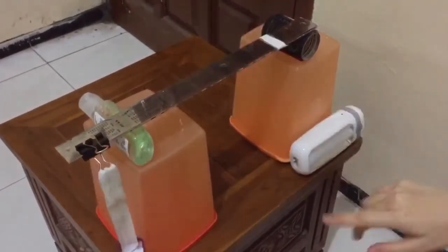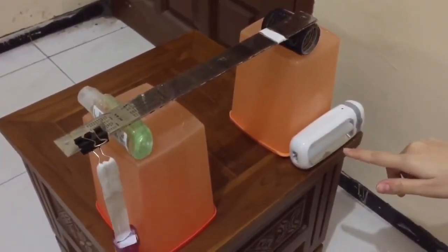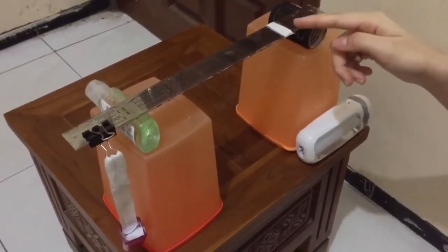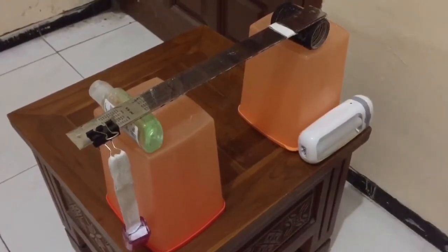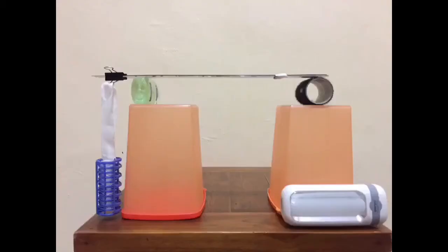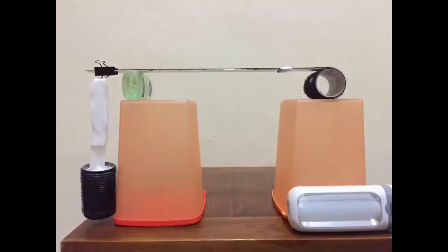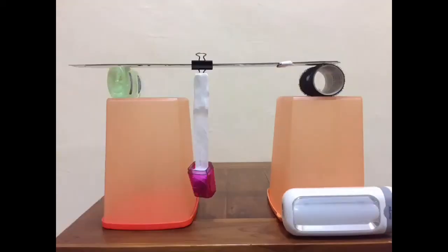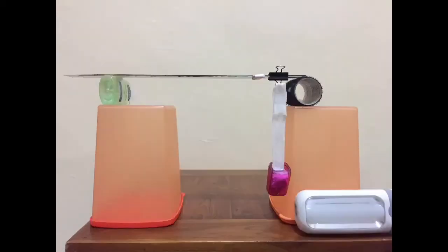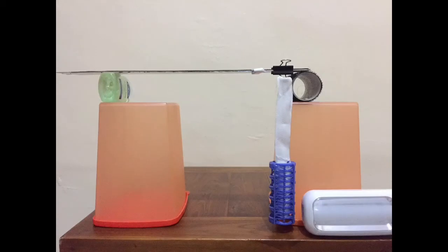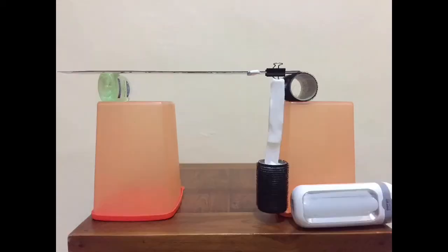After that, the display meter will show the shear force at this section, the X-X section, and the value we record on our laboratory sheet after multiplying it by -1. The experiment is repeated by increasing the load to 200 gram and 300 gram and moving the loads to 140 mm and 380 mm from point B. The same principle is applied to conduct the experiment of shear force due to UDL and superposition.